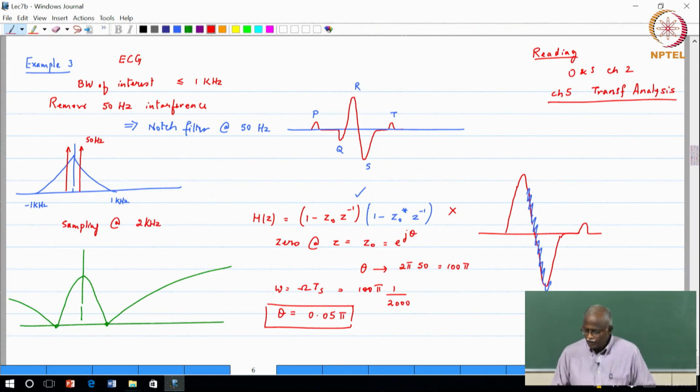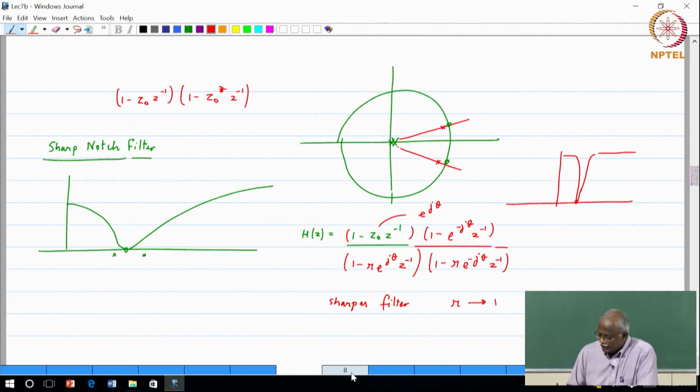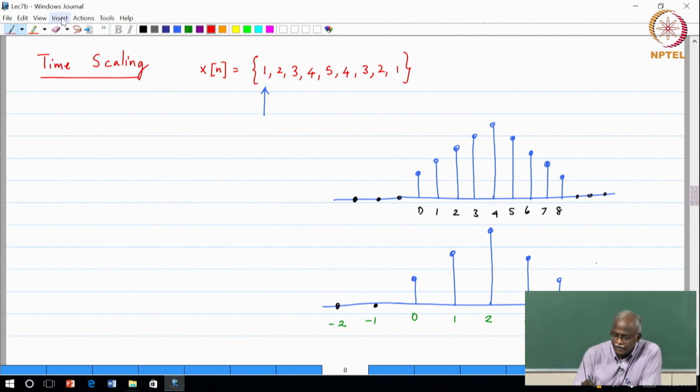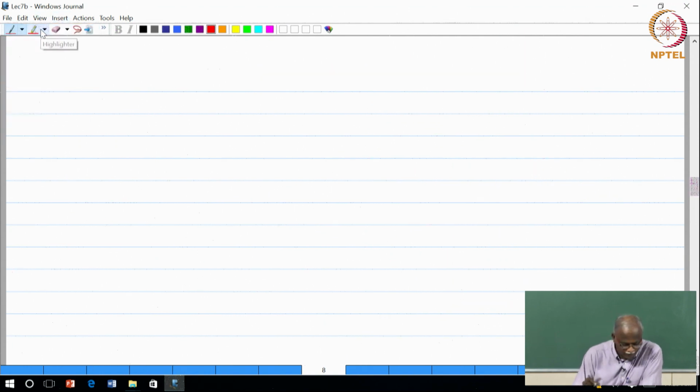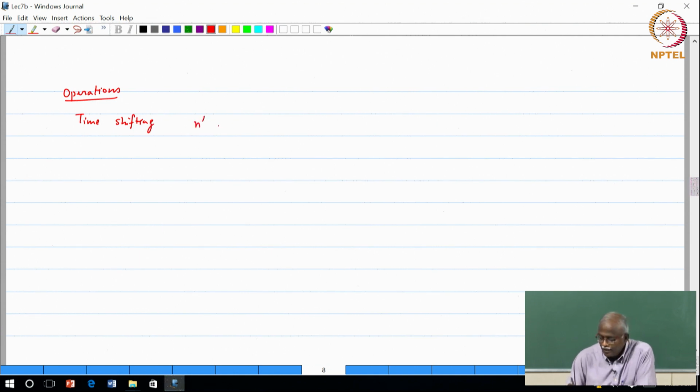Okay. So, let us move on to the new material for today. Let me just mention one more point. The various operations that we have looked at, the reason we are repeating this is because one of the operations is what we are going to be focusing on. One is time shifting. Time shifting says that you are going to change your time axis to n prime, which maps to the original index plus or minus n naught, where n naught is an integer.